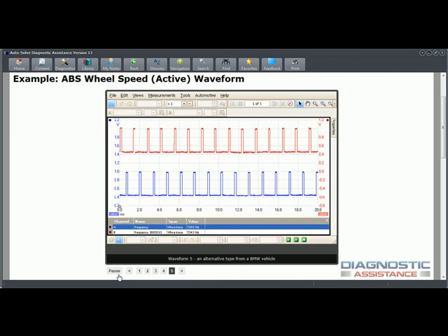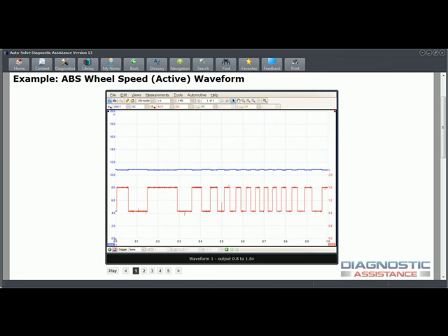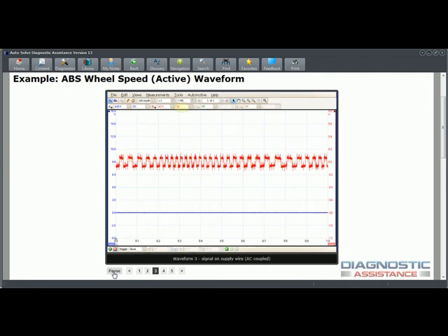If you wanted to pause those, obviously you can pause the waveform, you can play backwards through the screen to find the one that you're interested in, or you can have them running through in a sequence. This is then showing the waveform output. We can see the 12 volts in blue, or the signal supply, and on there we've got this very small waveform, and then down below we've got the signal waveform. So I play that for a second, you'll see it scroll through and show several other conditions or measurements from that type of component.